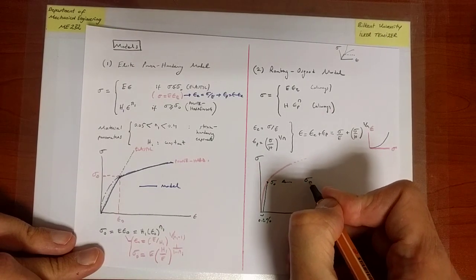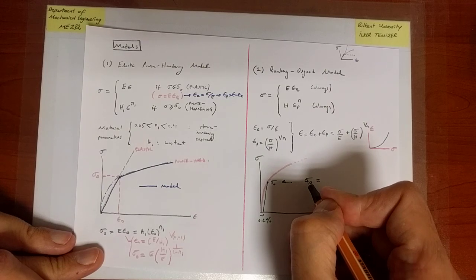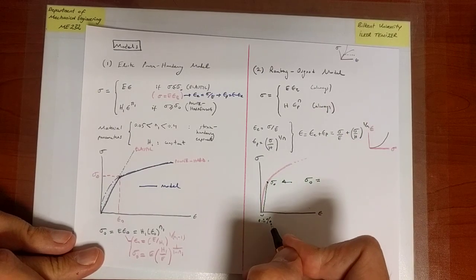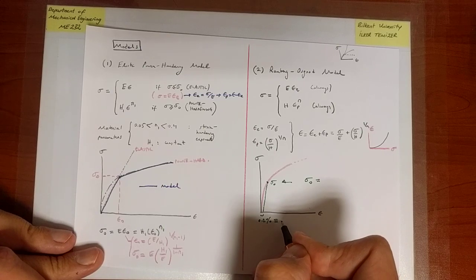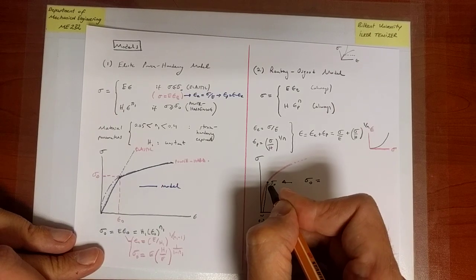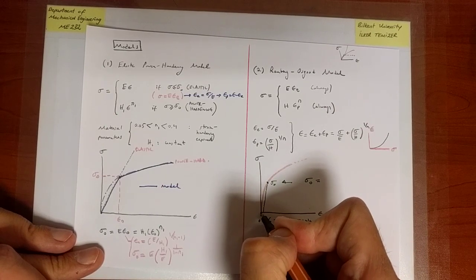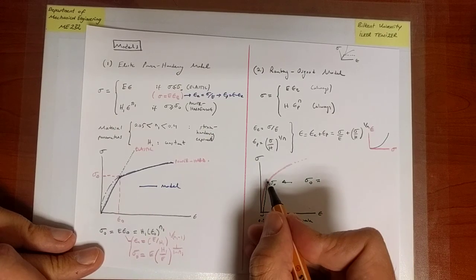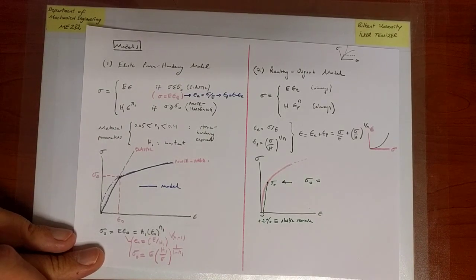The yield strength is the stress at 0.2% offset. What is that offset? That offset is plastic strain. Remember, what we've said is we unload at some point if there is appreciable plastic deformation, and that appreciable amount is 0.2%, then that stress is the yield stress.